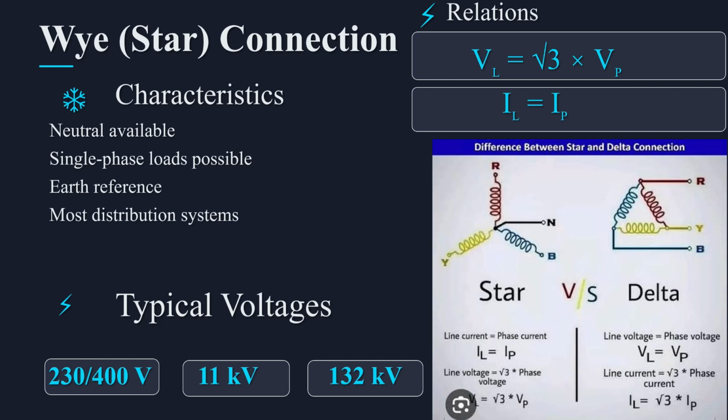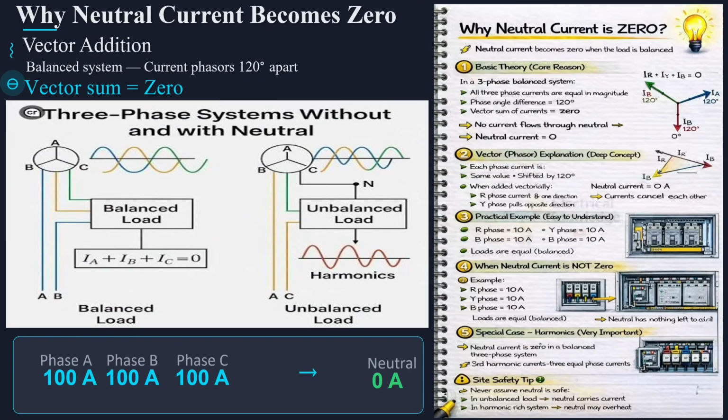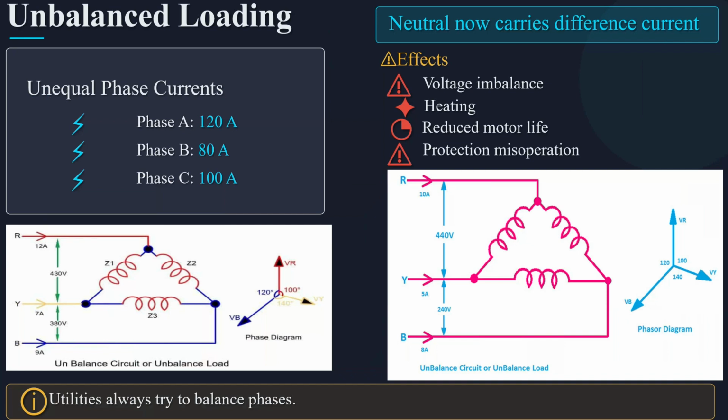System operators observe frequency, transmission line loading, transformer loading, bus voltages, active and reactive power flows, voltage stability margins, oscillation damping, reserve generation, equipment status, and contingency security. Every second they ensure that electricity generation precisely matches consumer demand while maintaining secure operation following equipment failures or unexpected changes in renewable energy production. Their decisions are essential for preventing overloads, maintaining voltage stability, and avoiding widespread blackouts.